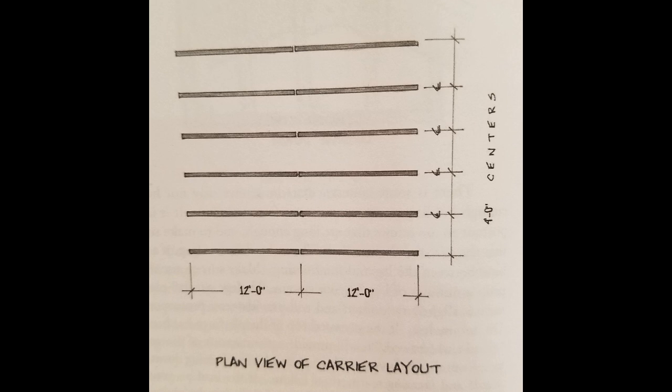There are often times in which you will also want to create a raised platform or a raised deck. And the way you would do that is basically creating stud walls. This image here is a basic structure or layout for a 24 by 24 foot section. And these little 12-foot stud walls have been built and spaced out evenly to allow all your platforms to be laid on top of all of these stud walls.